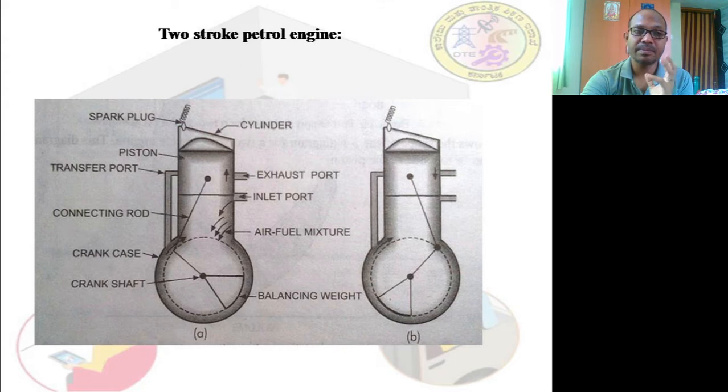The mixing of the petrol and the air comes with a particular air fuel ratio. With this proper air fuel ratio, the charge will enter the inlet port of the cylinder. Then it will not enter the cylinder, it will enter initially into the crankcase. Please see it carefully, the arrow marks are showing the downward movement.